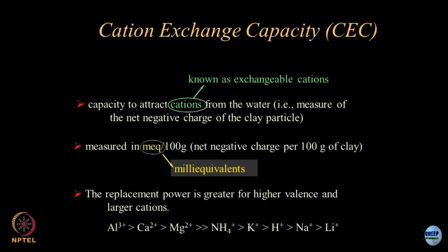By definition, the cation exchange capacity of the clay particles is the capacity of these particles to exchange cations with the environment. So, suppose calcium is present and sodium is available in the solution form, what will happen? Because of isomorphous substitution, the sodium tries to dislocate calcium, which it cannot do. Imagine a car cannot dislocate a truck which is parked in the parking space. So, these concepts are the order of the day. Those who are into R&D related to geomechanics and different subjects use these concepts quite a lot, creating different types of filters, liquid phase, gaseous phase and so on.